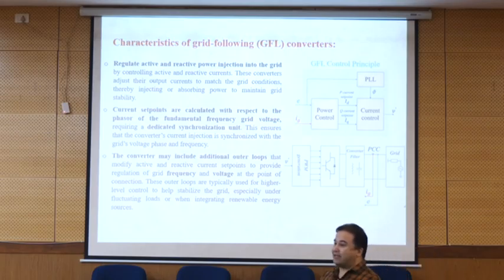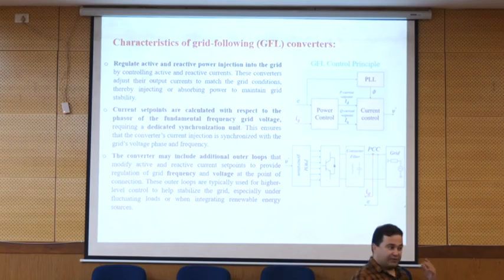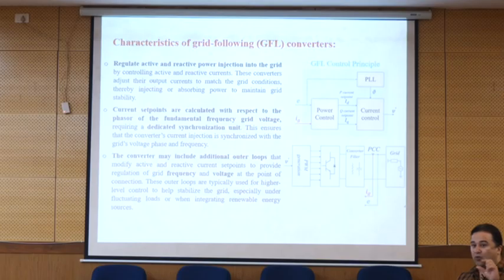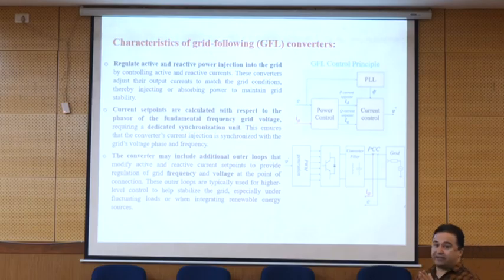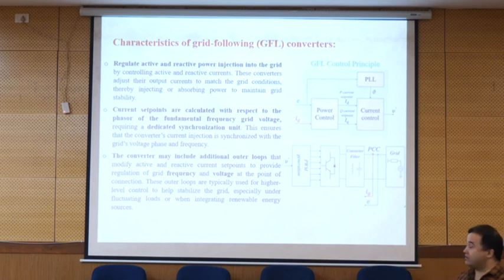Later we can see that, because the voltage is constant or must be constant, the active power is somehow related to the current, and the reactive power is also related to the current. So in fact, we can control P and Q based on the current.